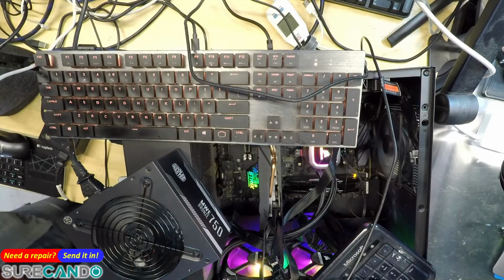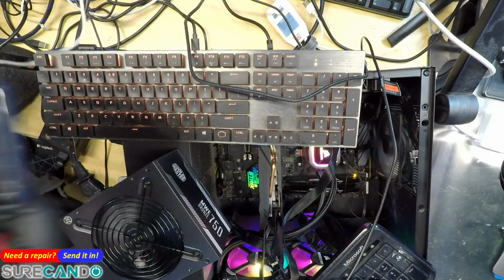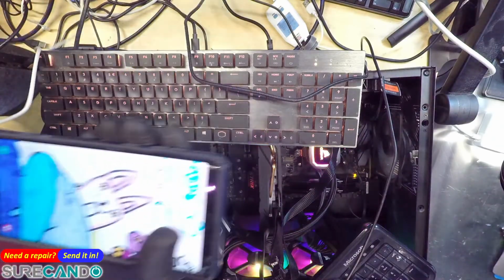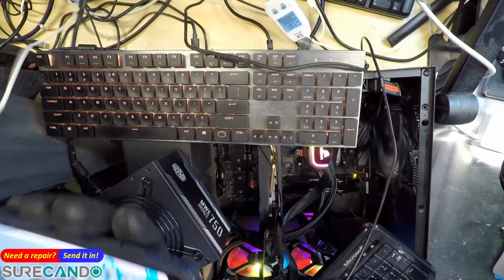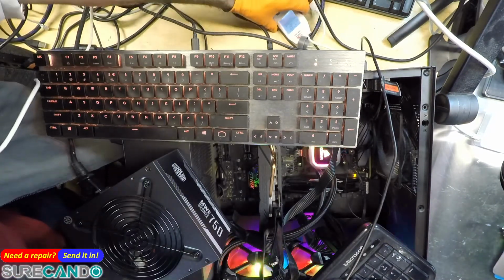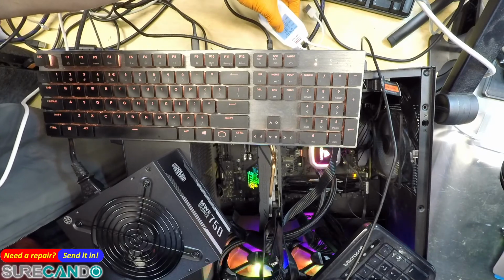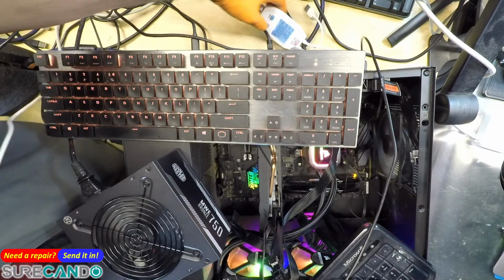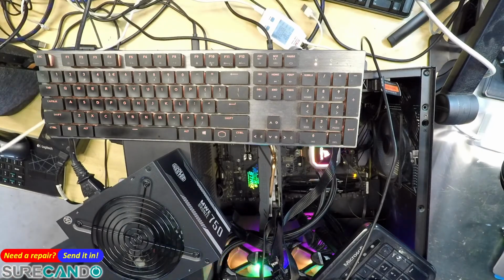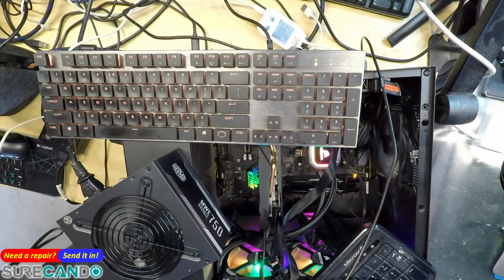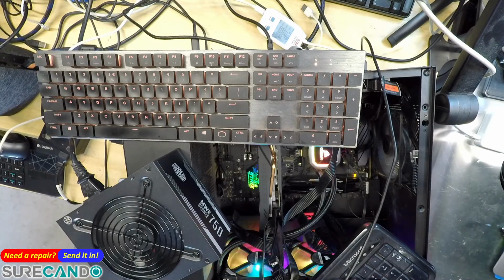Charge a mobile phone. So the phone is currently charging, and it's connected through there into the Type-C, and we're getting 0.4 and 1.18 amps. Beautiful. Yeah, definitely it's the power supply. Haven't seen this issue before. It's a really weird one on a 5-volt rail especially. That indicates either design failure or something weird.